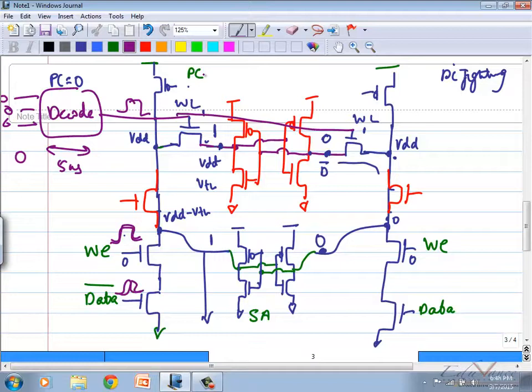You are not expected to design this, but this part you will have to take into account because you will be writing the test bench, meaning you will be the memory controller. You will be acting as the memory controller. You don't have to design a memory controller, you have to act like the memory controller. First set precharge to 0, correct, then give the address, then decide when to give write enable. All of that you people have to work out. Understood? Yes or no?